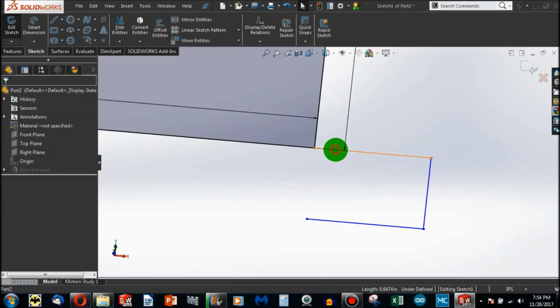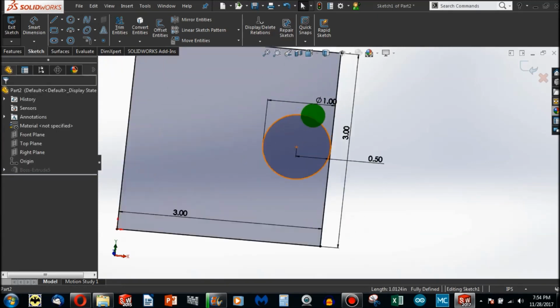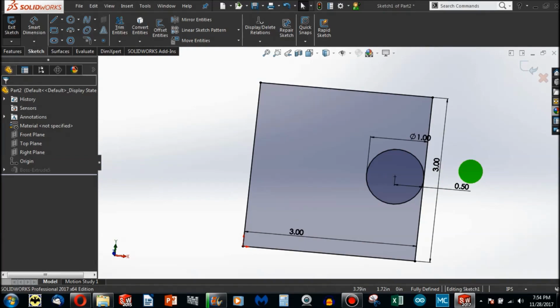So these are things to keep in mind when you have problems with geometric conditions or zero thickness. Just move things over by negligible amounts if you want them this way, and they'll fix. And this is such a minor change in your sketch, it wouldn't even reflect a manufacturing tolerance. With that, I'll see you in the next video.